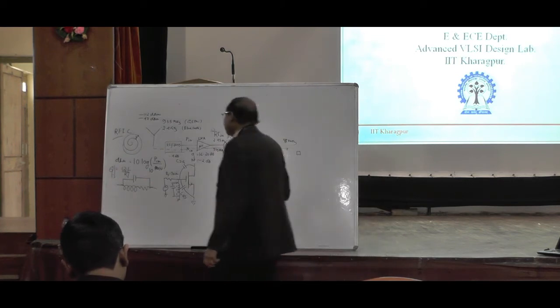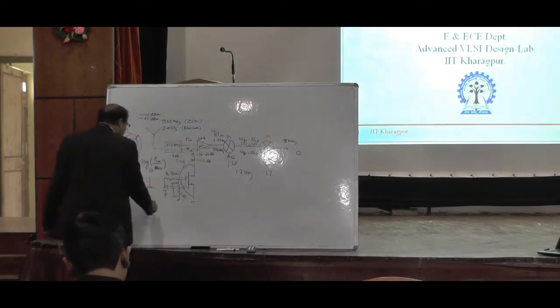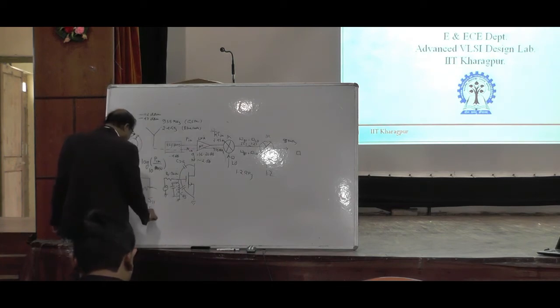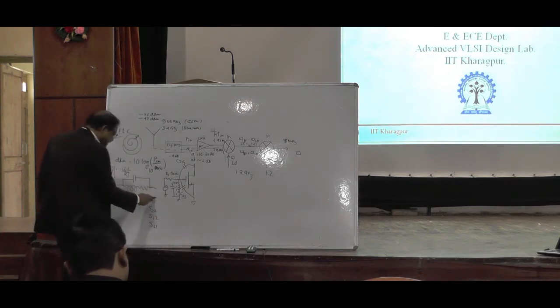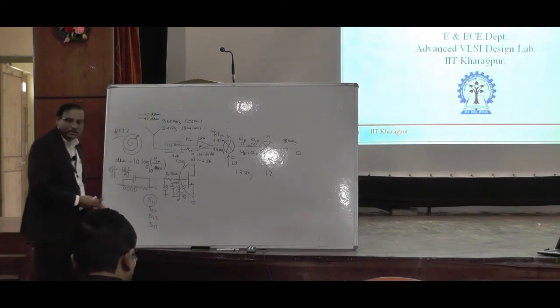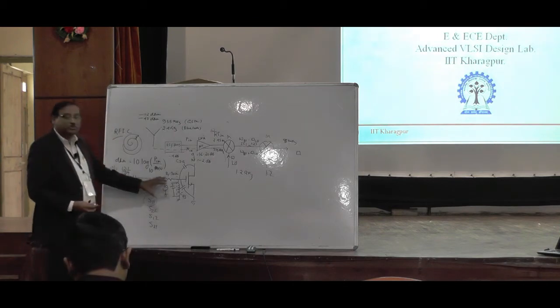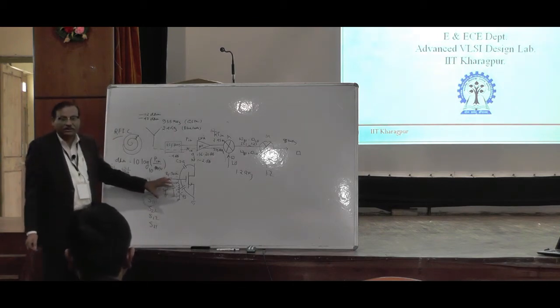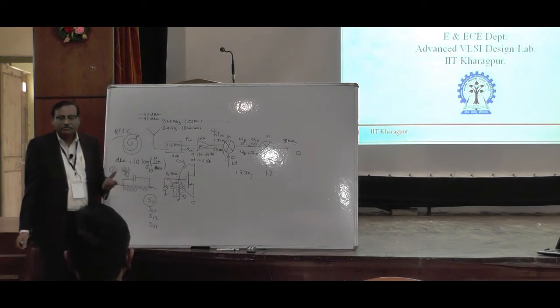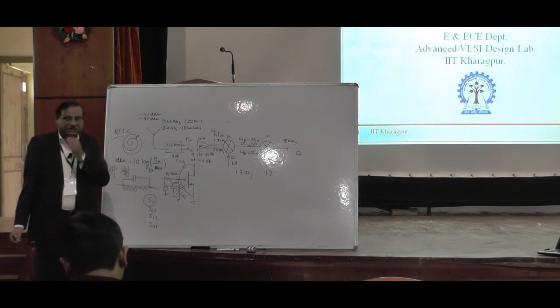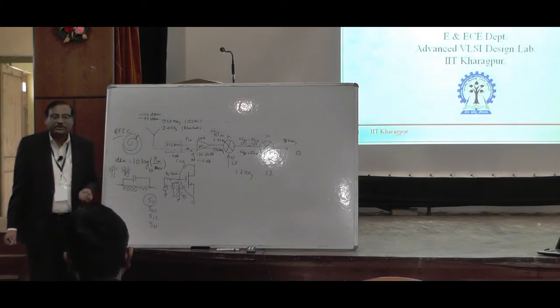If you look at the practical sense, you are measuring a two-port model, the scattering parameters S11, S22, S12 and S21. This S11 I am talking about, the input reflection, you need at least minimum minus 20 dB. How minimum? Minus 16 to minus 20 dB.